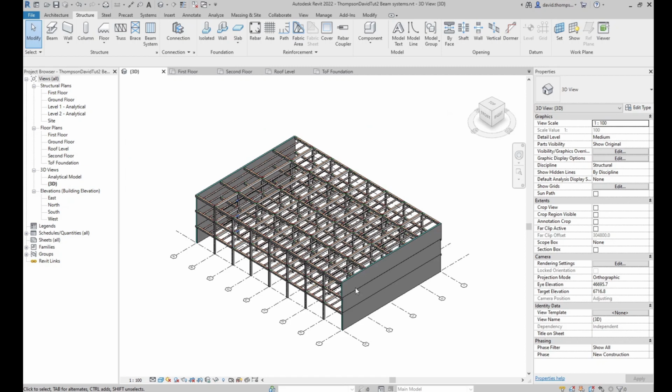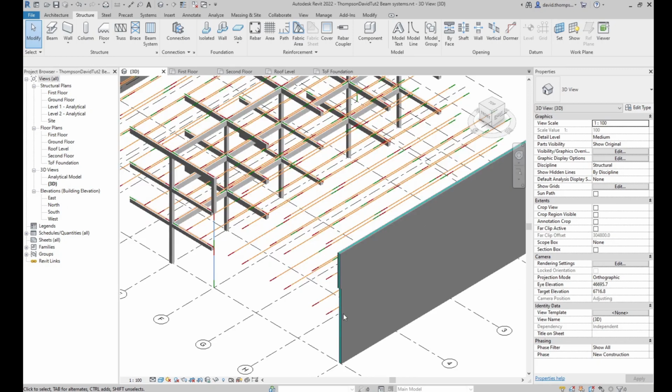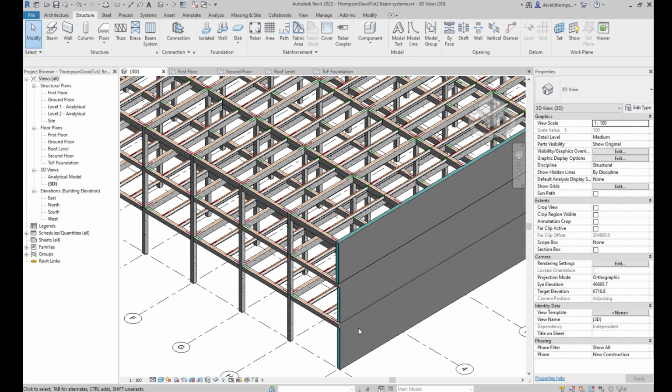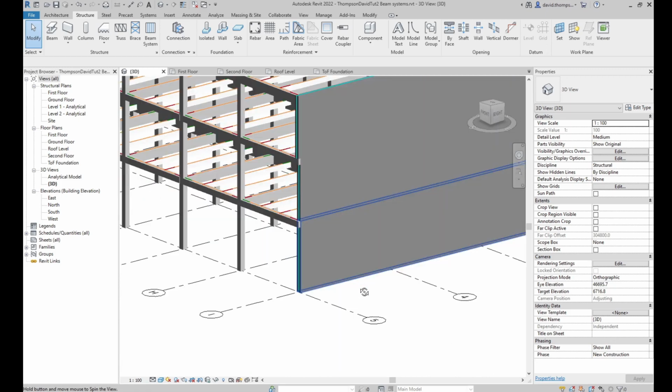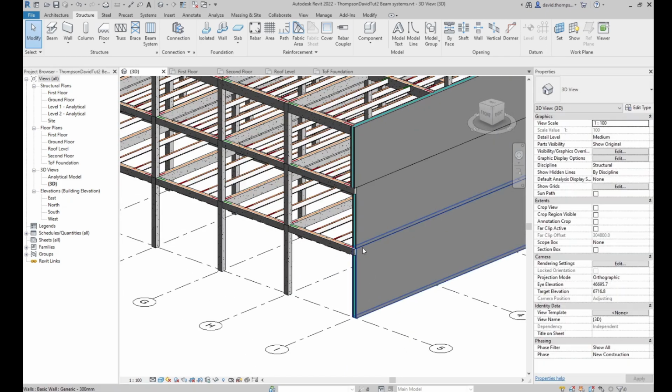Okay, so hopefully now your wall should look something along these lines. If you put them correctly, they should be something like this. Now I made a deliberate mistake here because it's something that you might have made yourself. Just for demonstration purposes, when you look into the wall, what you might notice is that actually the end point of each wall is a little bit different. It's a bit off. You'll see the column or the beam on this floor is actually sticking out, but on the top floor it's going in.